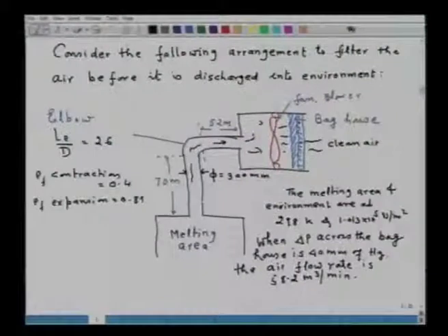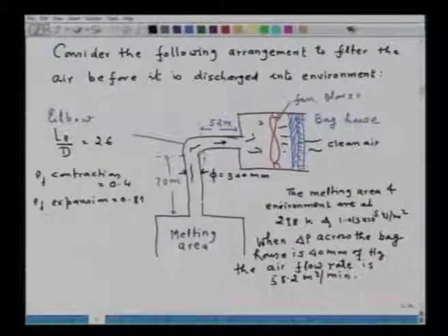So, again we have to find out what is the plane at inlet, and where is the plane at outlet. For the application of the mechanical energy balance, the input and output planes are important to show, because it is there you can make the mechanical energy balance. So, I will just draw the diagram to illustrate plane 1 and plane 2.